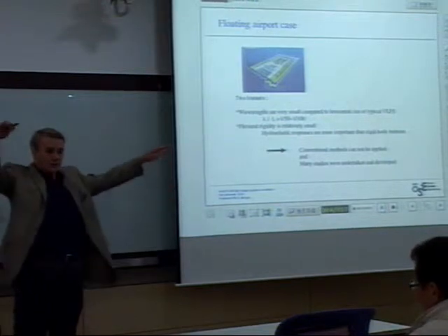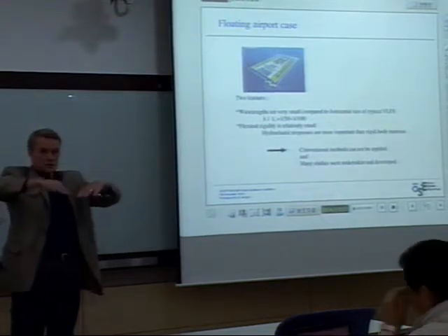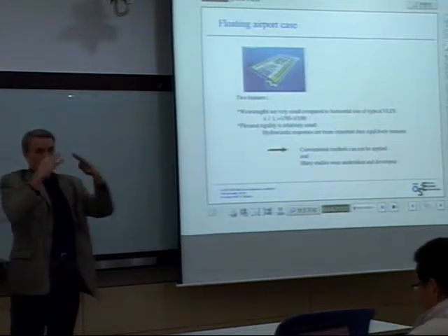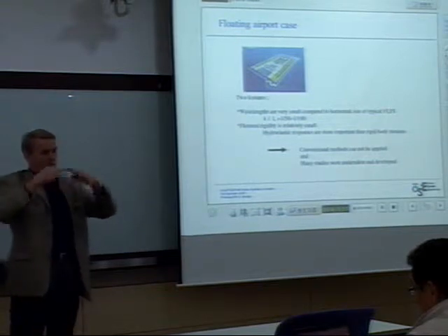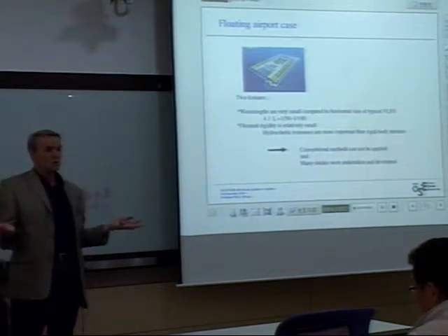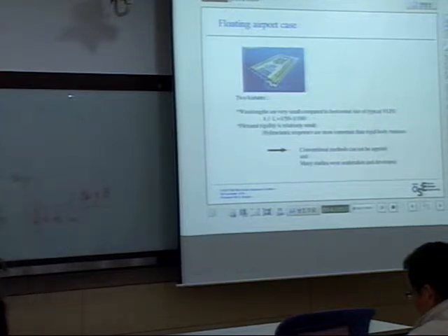The whole structure won't heave at the same time, but you'll have, of course, deformations due to the waves, and you have forces. So you have to design for these forces, even though the whole structure is not moving as a rigid body, because it's so large.